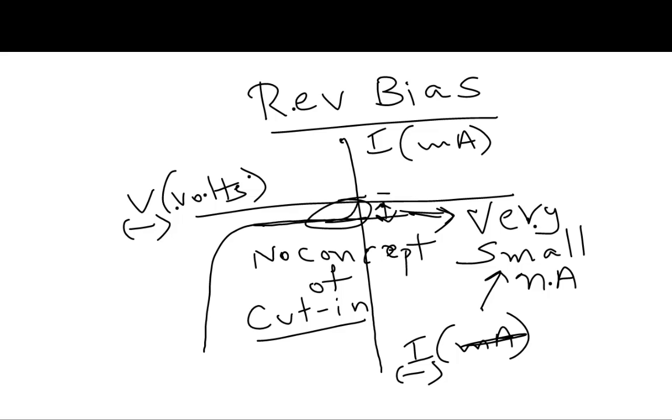Reverse biasing is quite interesting. If you remember, when we manufactured the diode, we added dopants or impurities to create P and N junctions. This made uneven areas with excess carriers, and we called them majority carriers. We did not add or remove anything to create minority carriers, because the dopants only created more majority carriers.